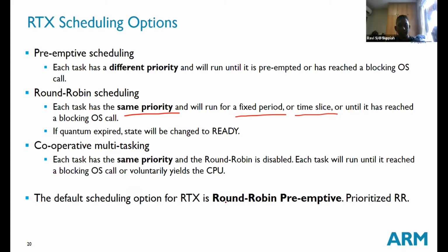So in summary, RTX itself is known as a round robin preemptive scheduler. Again, you must be mindful of how the scheduling system works for the RTOS you're working in. The preemptive nature where a higher priority task runs, by default all RTOS have that. But this round robin behavior may or may not appear in some other OS. For example, if you take Micro C OS, they don't have this as a default. They follow strictly that whoever is highest priority will always take over the CPU.